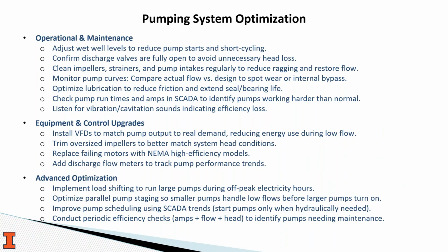For more advanced strategies, utilities can consider implementing load shifting. So this is where you run larger pumps during off-peak electricity hours and use more energy efficient pumps when electricity rates are a little bit higher. This again reduces your energy costs overall while maintaining your current equipment.